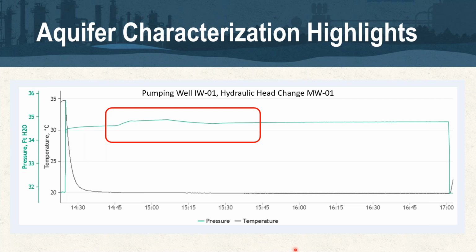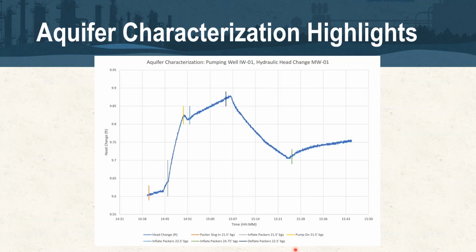So with a click forward, we can look at our other data from the time of performing actions on the site, and then see with a little more resolution and investigation here, looking at these individual changes with the plot. What we see here is that in this particular case, monitoring well 1 did not particularly respond with the pumping test itself to a significant degree, but what it did show was that the water within MW1 behaved very similar to what you would see with a falling head test on a standard slug test.